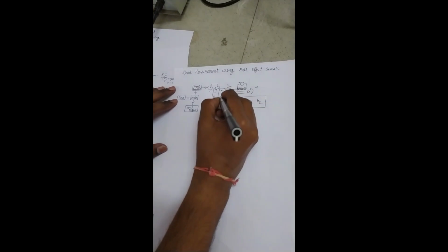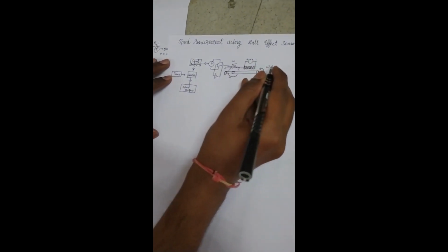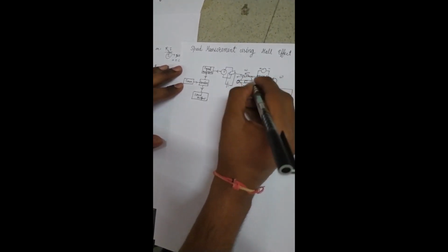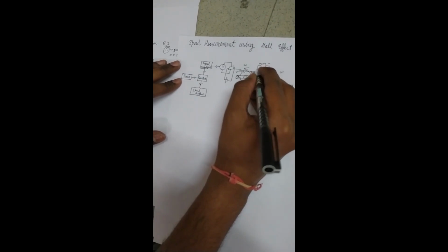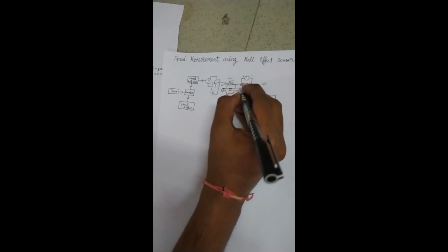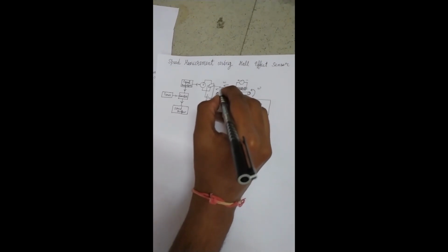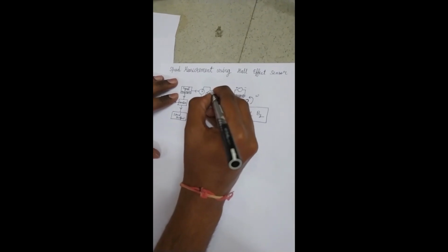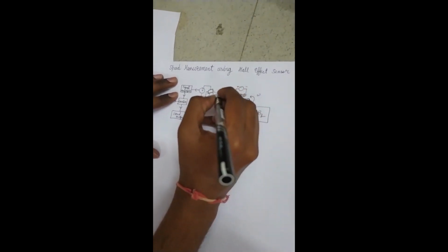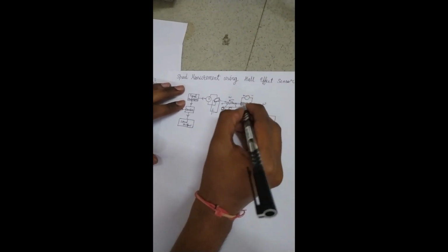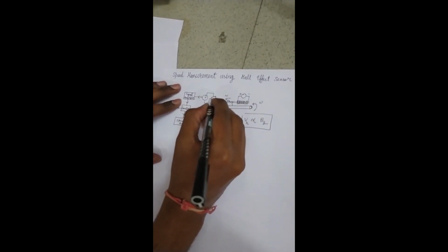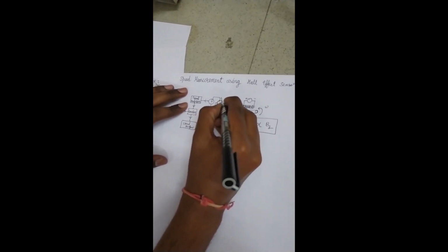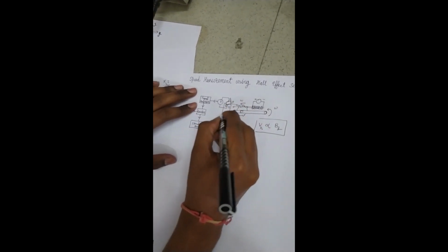So we have a shaft which is rotating with a speed omega, and with the shaft we have attached a metal tooth wheel, and this metal tooth wheel is nearby to a solenoid which produces an almost linear magnetic field, and beside and after this we have a sample in which we will study the Hall effect. What happens is that due to magnetic field, there is Hall voltage set up across these terminals A and B, and we apply current across terminals C and D.